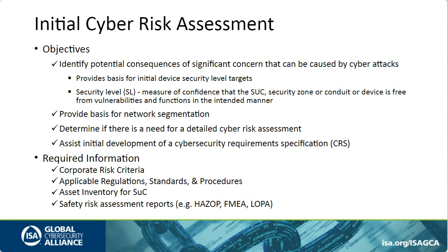A key item is to have an asset inventory for your system under consideration, and you also should have those safety risk assessments that came out of methodologies like HAZOP, which stands for Hazard and Operability, FMEA, which stands for Failure Mode and Effect Analysis, or LOPA, Layer of Protection Analysis.